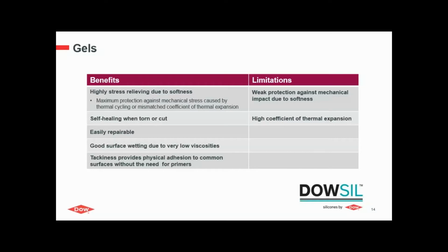What can be seen as a limitation is the protection against mechanical impact, simply due to the softness of those materials. And what also needs to be mentioned, they have a quite high CTE. So in case you fill up your module to the top and put a lid on and screw it down, at temperature exposure, those materials will put a lot of pressure in your module. So it can lead to the damage of certain components up to the breakage of the whole module. So this definitely needs to be considered when using this kind of material to pot your module.